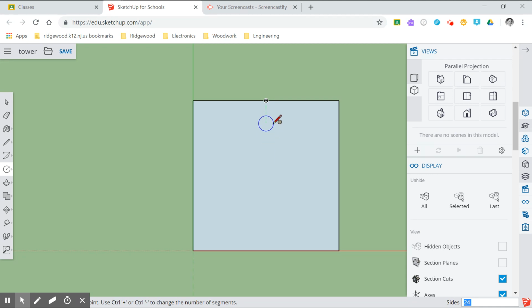In this case, since I need the center, I need to reference both midpoints. So I need to hover over one midpoint, hover over another midpoint, and draw out my lines. And usually it will work that both lines will come together. And if you see that both the green and red is dotted, and therefore I have the center, I now click there. I've established the center.